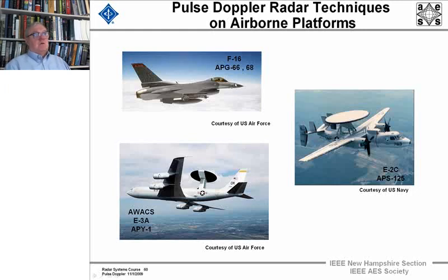You've got a small area in that nose, so you've got to have a small antenna. And if you want decent beam width, then that's going to constrain you to small wavelengths. And those small wavelengths are going to constrain you to a certain place on the ambiguity diagram. And that's going to say, uh-oh, I've got to have these PRFs and these range ambiguities or whatever. And that's going to say a lot about what waveforms you can use.